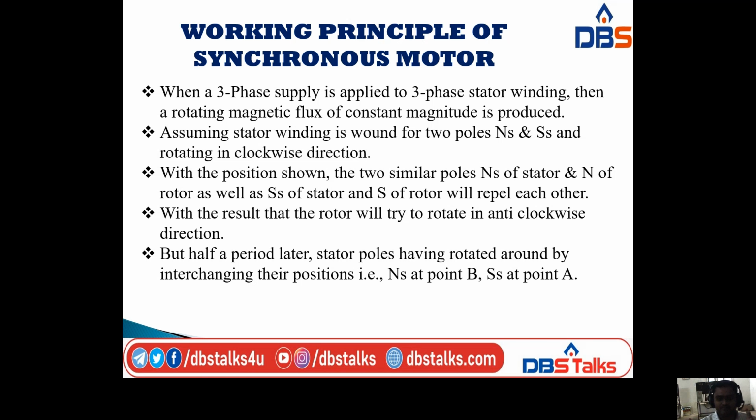Previously the stator poles and the rotor poles were in the same direction, but half a period later the stator poles have rotated around by interchanging their positions, that is N_S to position B and S_S to position A. That means in the previous half period, N_S was at position A and S_S at position B, but in this half period the stator poles have interchanged their positions, N_S at position B and S_S at position A.